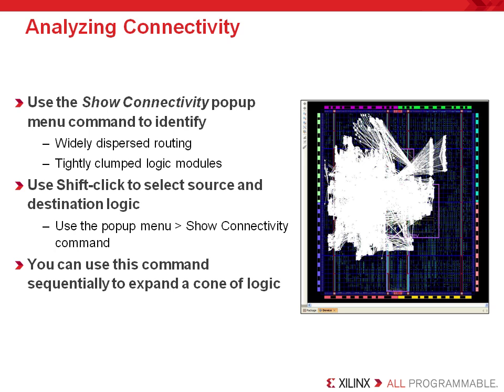The PlanAhead software has extensive logic expansion, selection, and highlighting capabilities. These capabilities can be used to validate that modules are suitable to floor plan. For example, logic modules that connect to logic throughout the device may not be suitable for floor planning, while tightly grouped and self-contained modules are suitable. Routing congestion and timing inconsistency can be alleviated by floor planning logic outside of the critical logic areas, preventing logic from migrating into the critical areas.